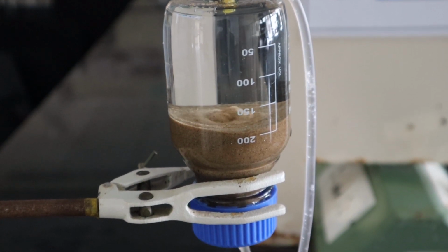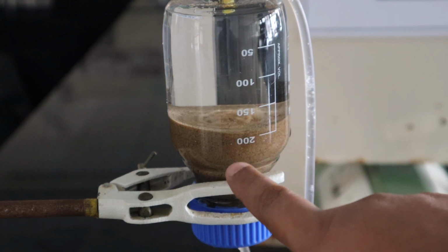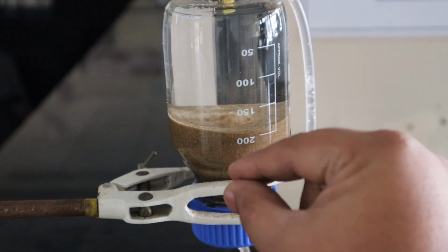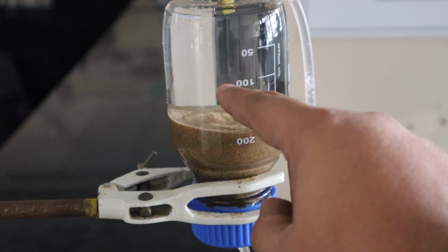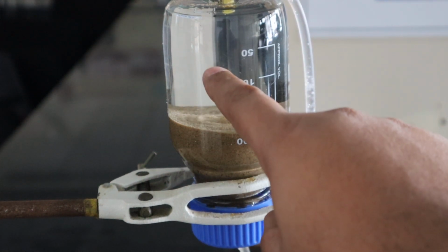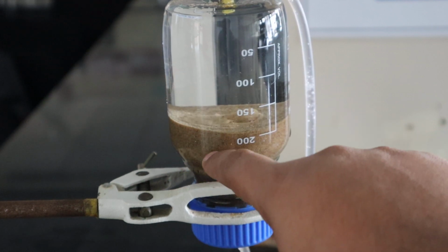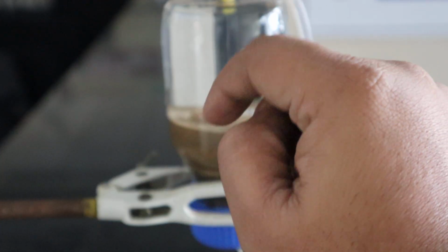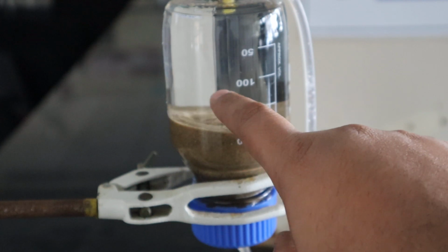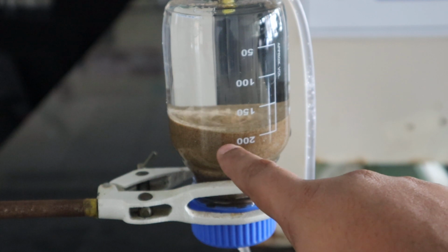Then what is the superficial velocity in such cases? You can see there are two things. One is the velocity here in the bed, which is different because it has less space because of the particles. Compared to here, the velocity is higher in the bed because as there is less space, the water will move very fast, because the smaller the area, the faster the water will go. Here this is called the empty tower. Here the velocity of the water is low compared to the velocity in the bed.